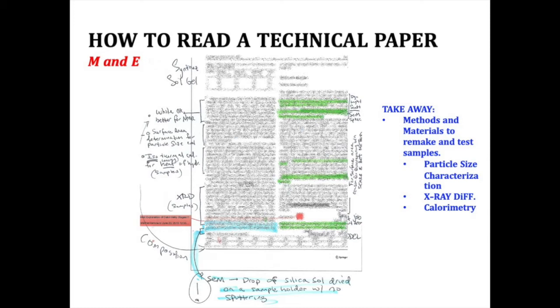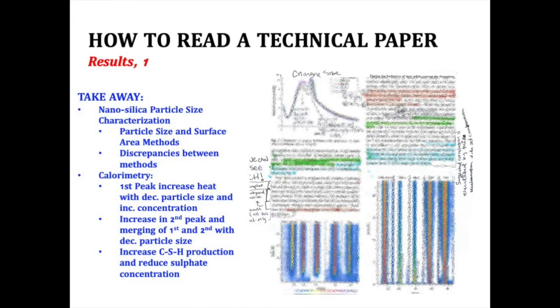I mean, just a really beautiful bringing the results together. And they also discuss the limitations, but another portion which I really like is they go into that merging of the first and second peak and how that is related to the AFm phase, and how that is only possible because we see a sulfate reduction due to this accelerated set of reactions, as well as an absorption from the silica surface area.